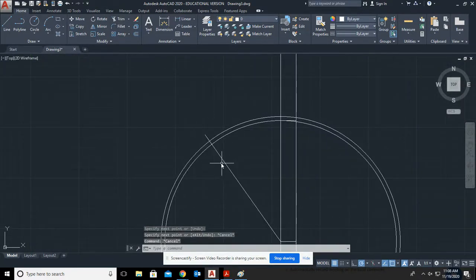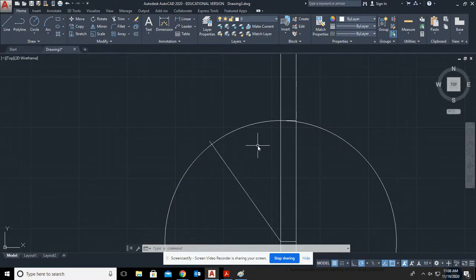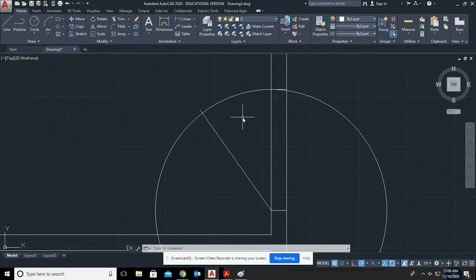Now this is the door, this represents the swing of the door, this represents the hinge, and this line, the width. I just offset out 1 inch, and the sole purpose of that was to give me something to trim to. Right there. Delete that circle. So this will stick out 1 inch further. On a print, normally you want things to stick out roughly 1/4 of an inch on a full-size print. For this particular case, I don't really care. We're just going to make it stick out a little bit.